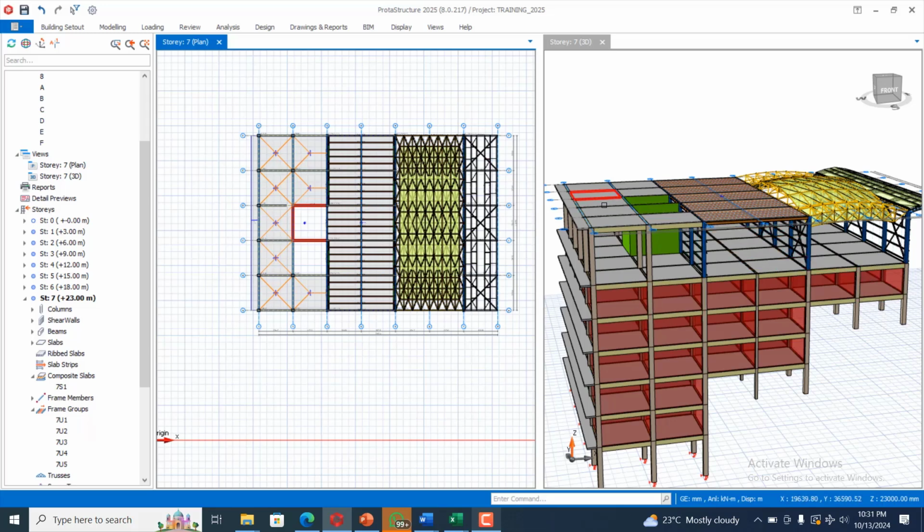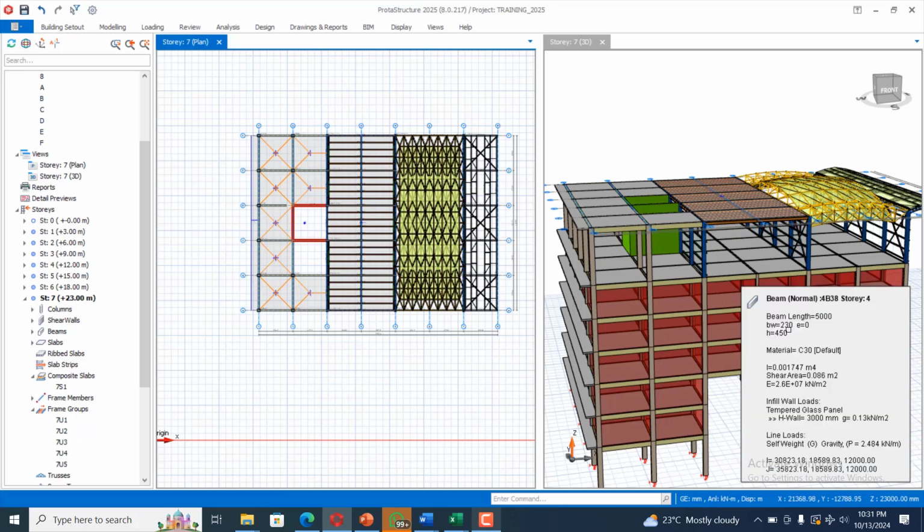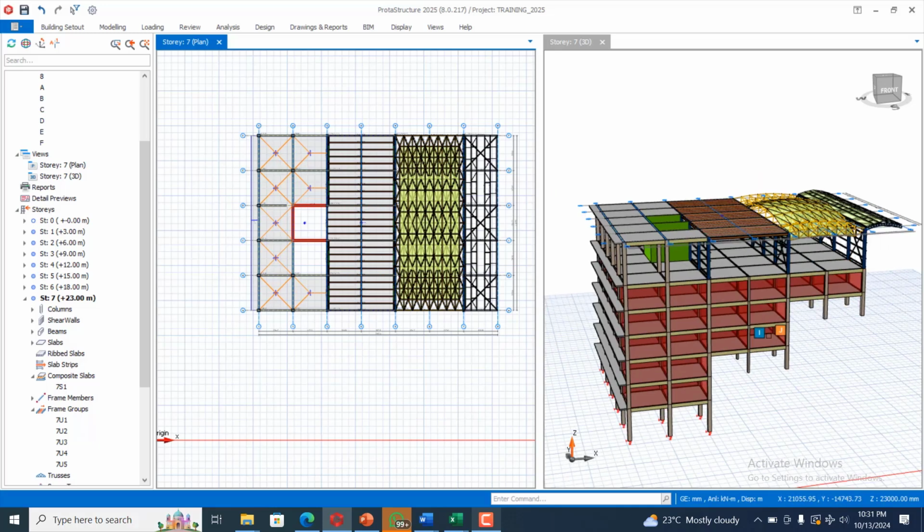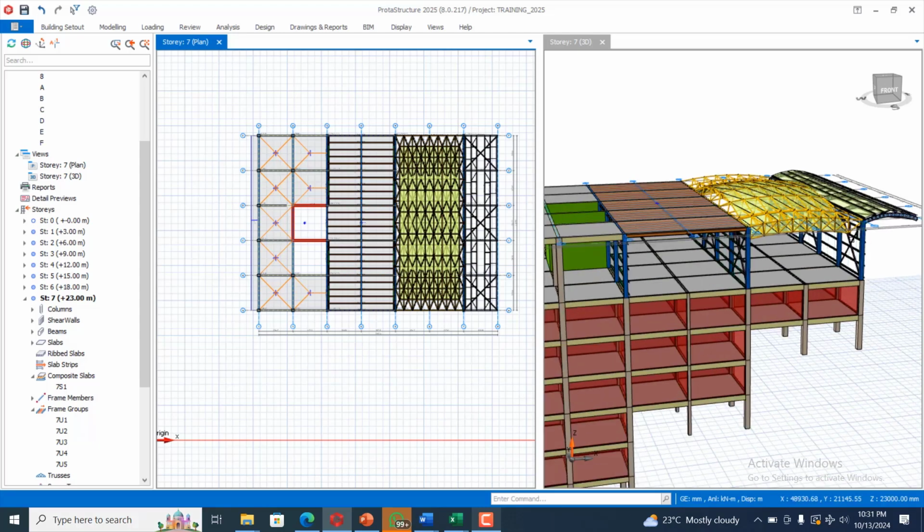As for this, we're just demonstrating, although this level and this level are not the same, because this is the starting point of this particular story. Like we said, you are not having a flat terrain, so this is the starting point. This is the ground floor for this, and this is now the ground floor for this one. So it's a staggered kind of foundation because of the terrain, assuming the terrain is like this.